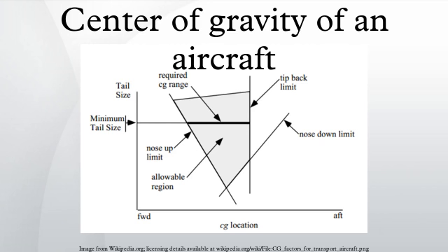Small lateral deviations of CG that are within limits may cause an annoying roll tendency that pilots must compensate for, but they are not dangerous as long as the CG remains within limits for the duration of the flight. For most helicopters, it is usually not necessary to determine the lateral CG for normal flight instruction in passenger flights. This is because helicopter cabins are relatively narrow and most optional equipment is located near the center line. However, some helicopter manuals specify the seat from which solo flight must be conducted.